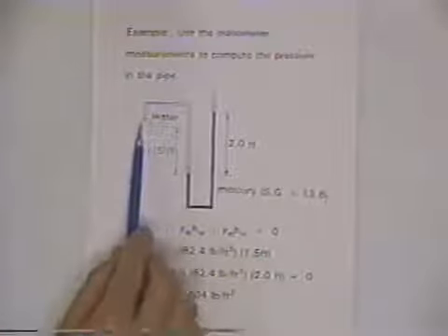And of course, to simplify the computations, we could just run a piezometric tube straight up and see how high the water rises in the tube, and that would do it too. It'd be a little inconvenient because the water might rise quite a few feet, and a manometer gives us a mechanism to make the measuring device fit into a reasonable space.